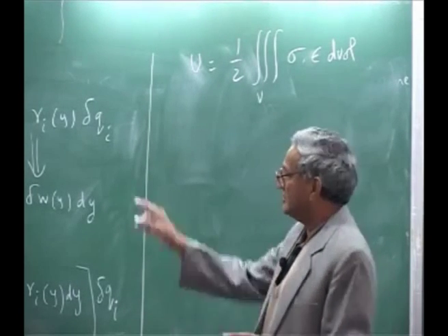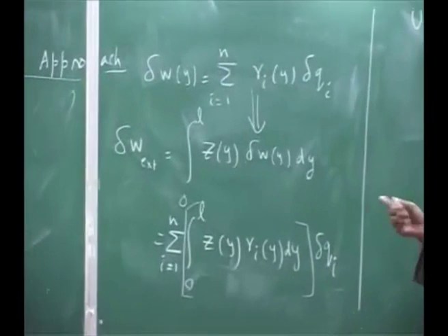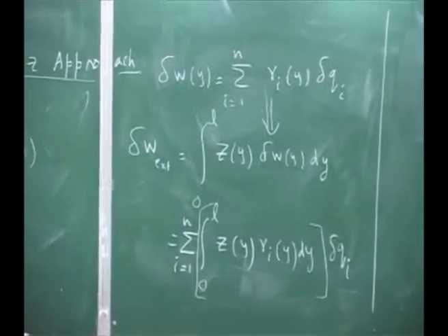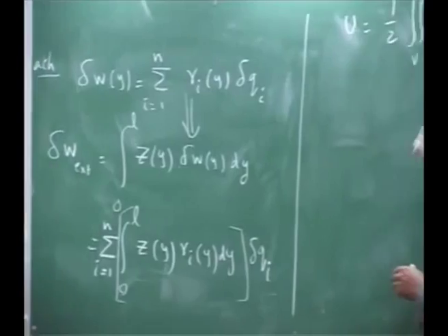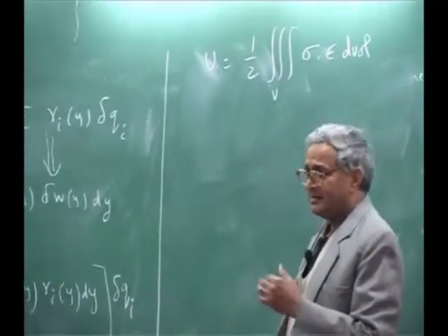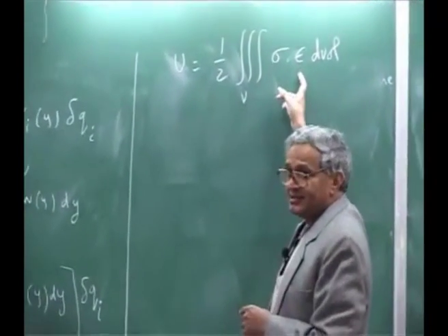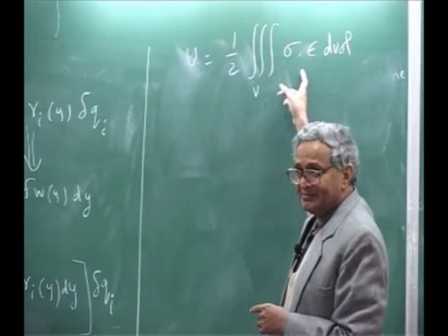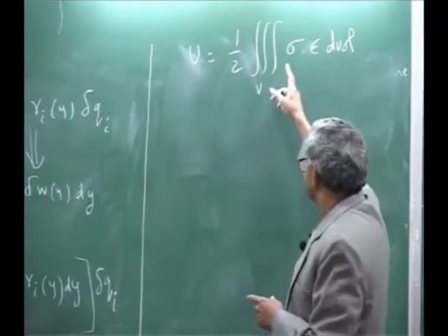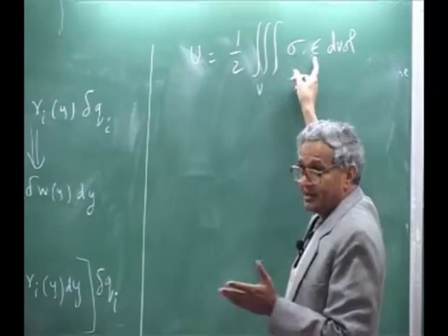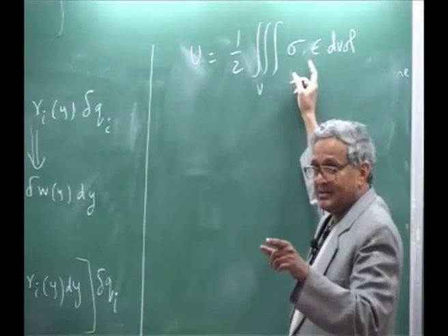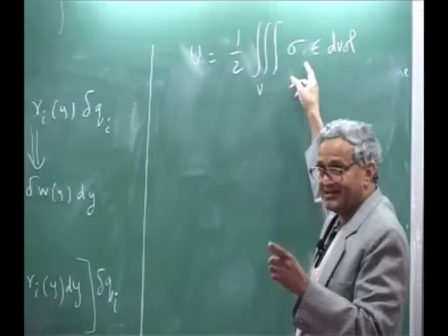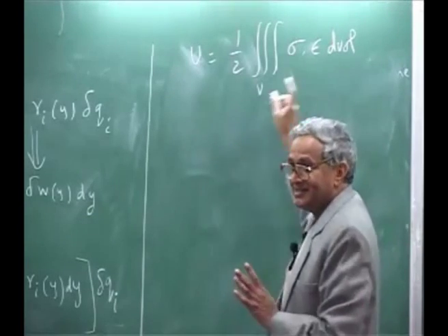If the beam cross section is some shape, then you will say, how do I represent my epsilon? And then that epsilon you will substitute here, and then you know stress is related to strain, because this has all the components. Sigma epsilon I wrote, basically it has epsilon xx, ij, everything. That whole summation is there.